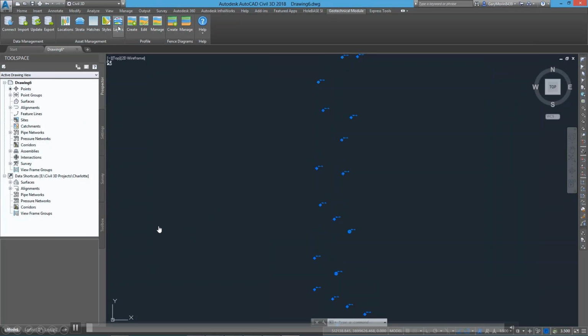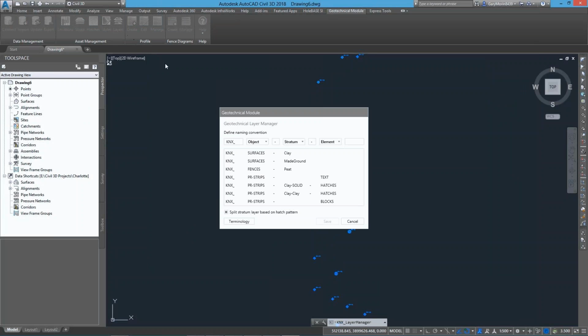You'll see we have this new layer command. If I click it, what we actually do here is define the layer naming convention. We have it by these various different lookup boxes and text boxes. In the bottom section below there you saw examples. So here, for instance, I'm going to start off really simplistic.